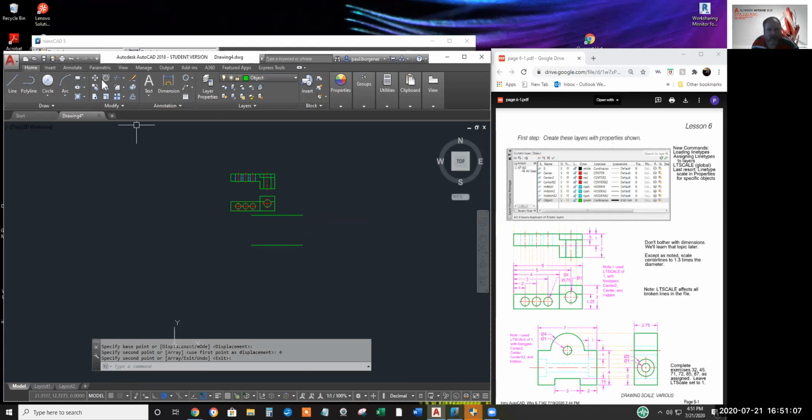I'm going to run out of space, so I'll move them both down. Let's see, the big arc is 4 units diameter. And again, some people might say the center of this arc is not located, but I'm confident it was created from the center of this hole, which is perfectly in line with the green lines to the side.